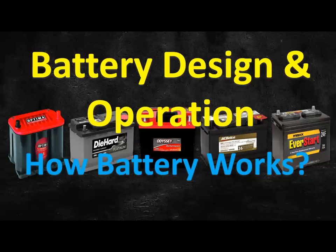For example, if the battery is gassing excessively, the charging voltage must be too high. You also need to understand that water is vented from the battery during the normal charging process. Therefore, only water, that is distilled water, should be added to the battery cells.